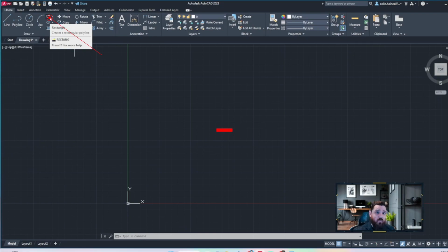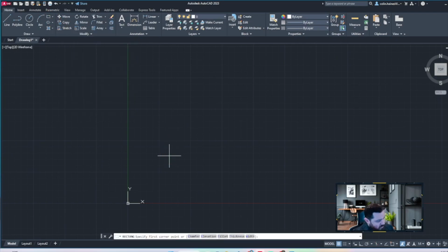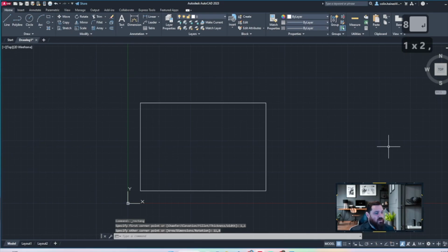With the rectangle tool, instead of having to type in several different coordinates, 4 to be precise, if you want something square or rectangular, you're just going to type in 2 sets of coordinates. So we will grab our first set of coordinates, which we've been starting with 1, 1. So why break the trend? And I want to make a 10 by 7 square. So let's go 11, 8. And there we go. We have our 10 by 7 rectangle, and we are looking pretty good here.